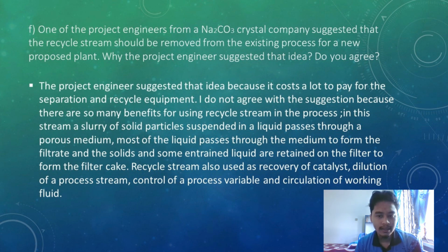In the filter, a slurry of solid particles suspended in a liquid passes through a porous medium. Most of the liquid passes through the medium to form the filtrate, and the solid and some entrained liquid are retained on the filter to form the filter cake. The recycle stream is also used for recovery of catalyst, dilution of process stream, control of a process variable, and circulation of working fluid. Thank you.